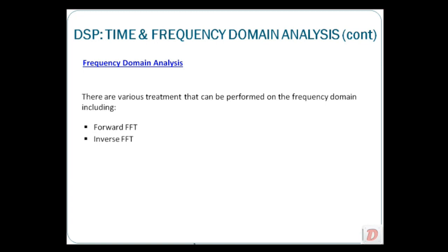Of course, with the inverse FFT, IFFT, it can also transform back to the time domain. So if you have a frequency domain signal, with this IFFT you can convert back to the time domain. It's also part of the analysis you can do. Sometimes it is needed to do some processing or filtering in frequency.